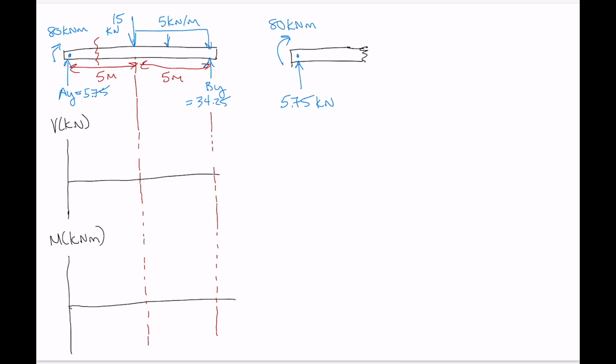And then we've got our internal shear force. And remember, don't think about which direction it is really in. Think about putting it in the positive direction according to the convention that we've assigned. So a positive internal shear force acts to rotate the section clockwise, so this needs to go downwards like that. And then we have an internal moment, and same deal, right?